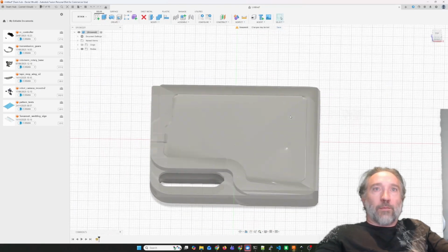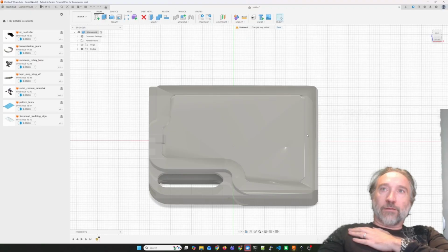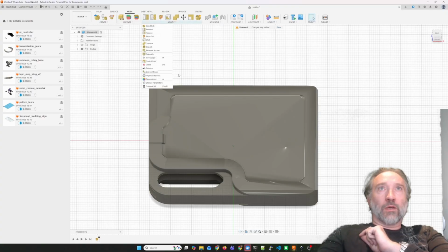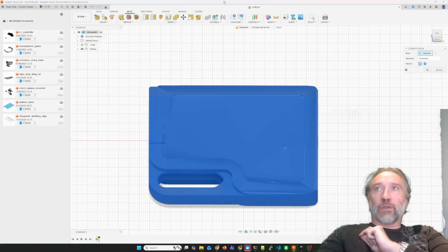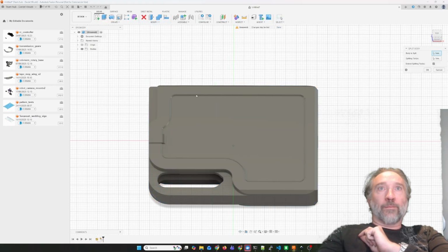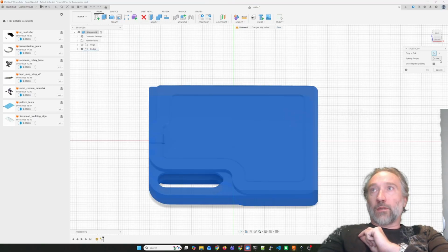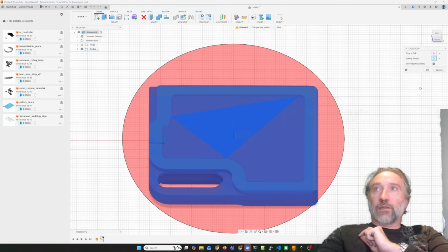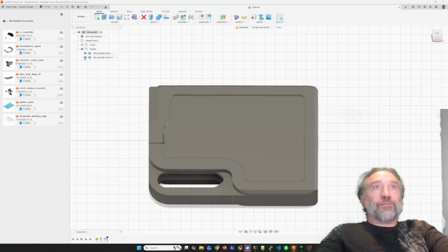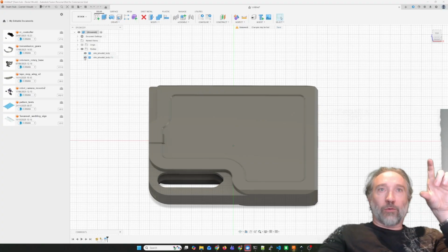So this is the mesh, and what I want is to fill this panel with a pattern. So we're going to convert our mesh into a body so that Fusion will let me work with it a bit better. We're going to split the body based on one of those faces. And so what that should have done is, let me take away that boundary, right?